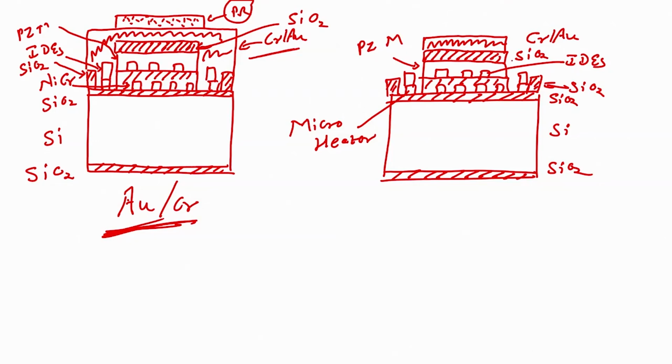Now, this is just a schematic to show it to you. You can also have photoresist in this particular fashion, so that your pads below the photoresist will not get etched. This should not get etched, right. This one and this one are directly exposed, and they are also interdigital electrodes which are made up of chrome gold. So, chrome gold can get etched if this is not protected with the help of photoresist.